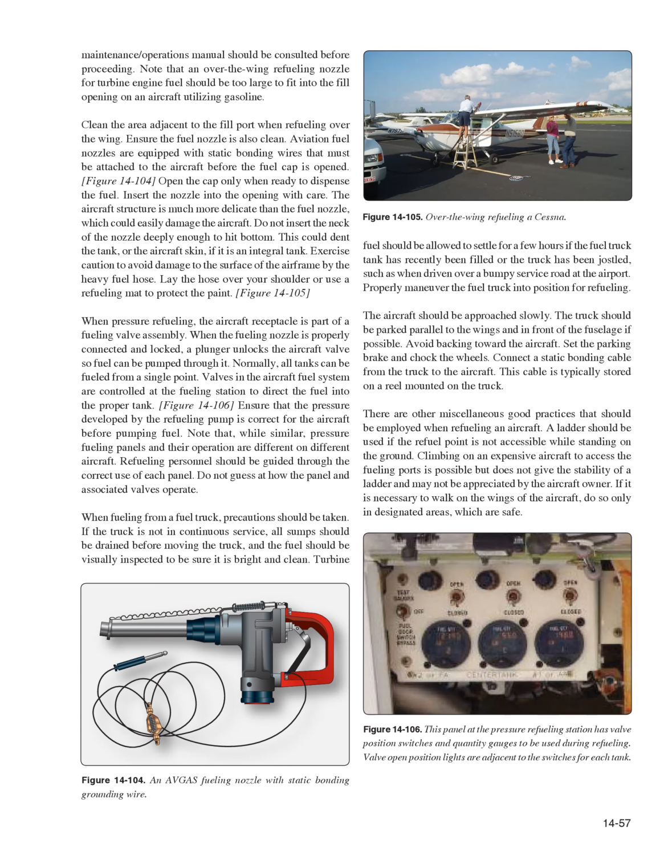Note that an over-the-wing refueling nozzle for turbine engine fuel should be too large to fit into the fill opening on an aircraft utilizing gasoline. Clean the area adjacent to the fill port when refueling over the wing. Ensure the fuel nozzle is also clean. Aviation fuel nozzles are equipped with static bonding wires that must be attached to the aircraft before the fuel cap is opened. Figure 14-104, open the cap only when ready to dispense the fuel.